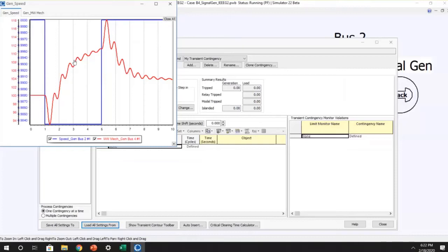Okay, so we use these all the time. Sometimes it's kind of fun to take a system and put an infinite bus on it and put like a 1 hertz signal out into it and just shake the system and see how it responds. You can get a good feel for what your models are doing.